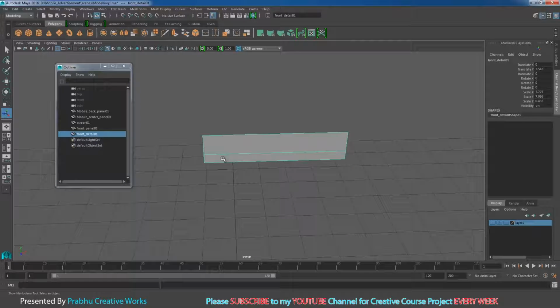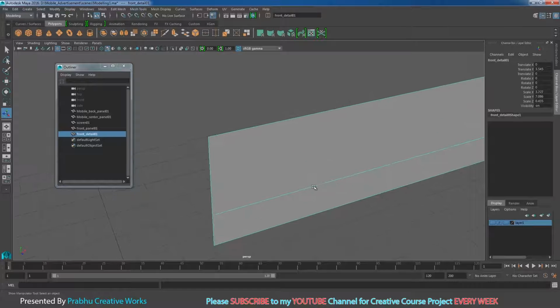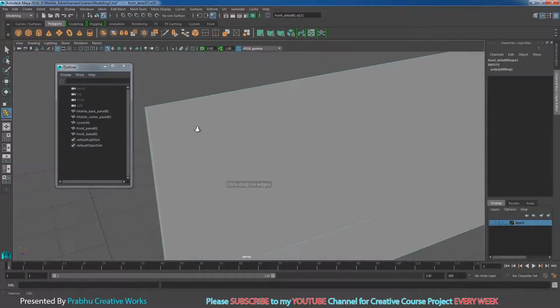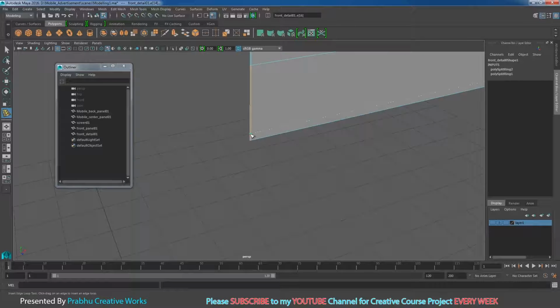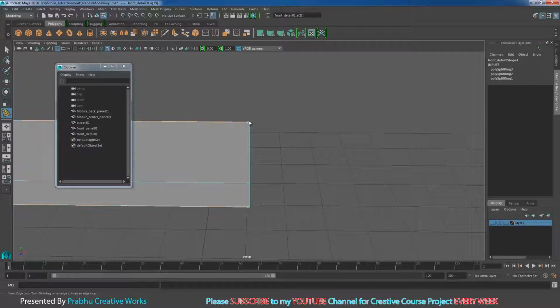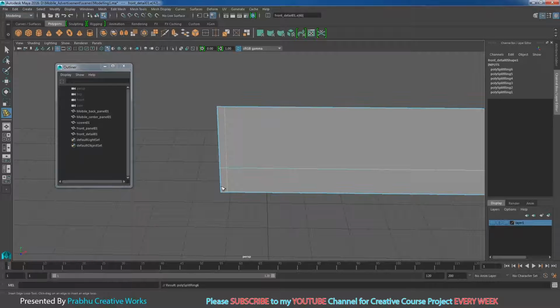So that means first of all you want to convert this mesh as a subdivision, and then you want to convert this as a NURBS. So before that, when you convert this mesh as a subdivision, it will be smoothened. So you want to insert edge loops very close to the edges, very close on all four sides. So like this, and then like this.